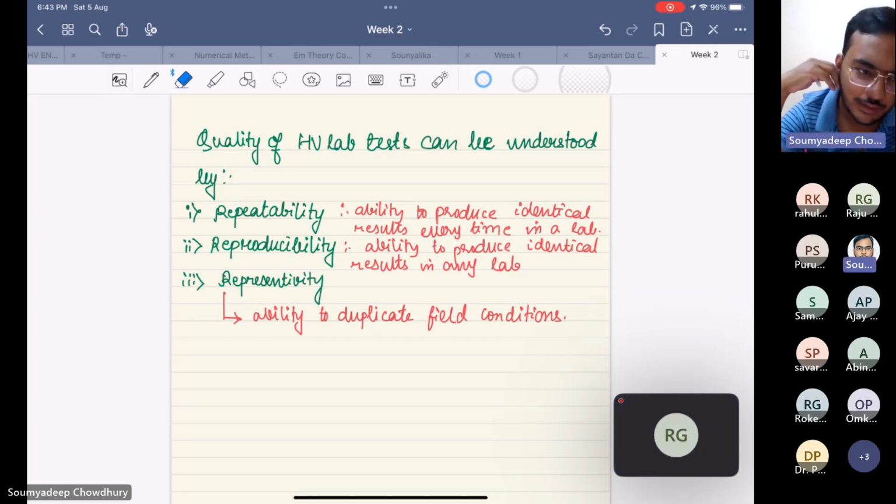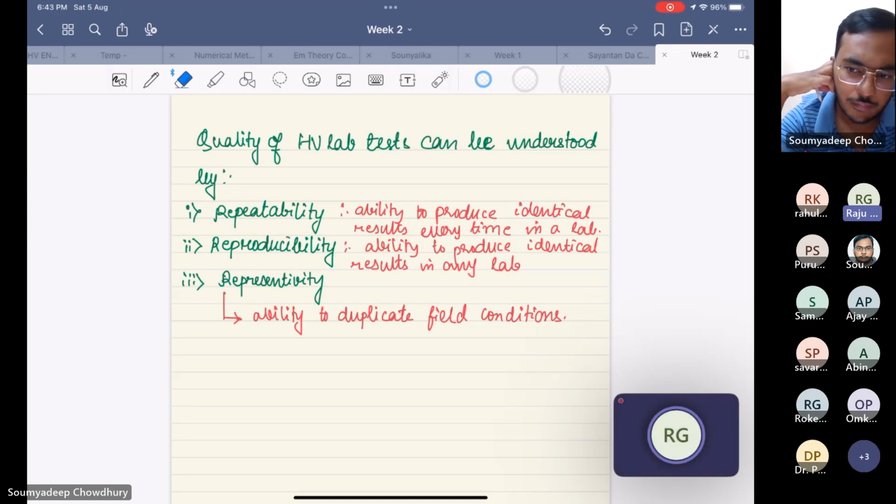Can you come once again, sir? Suppose you are doing the first test at a slightly higher voltage, that is 25% or 30% extra. When you are exerting a higher voltage, the property of the insulator will get deteriorated. And the next day when you are testing the same insulator at the same voltage, the insulation has already deteriorated. You cannot get the same results, no?